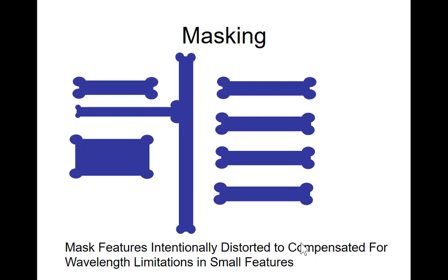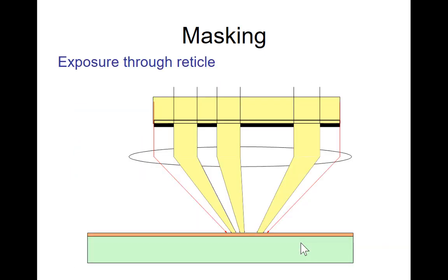Later on they do so-called computational lithography. They create a mathematical model of how the light, which you can think of as EM waves, travels from the mask to the wafer, following Maxwell's equations, and you get a transfer function.